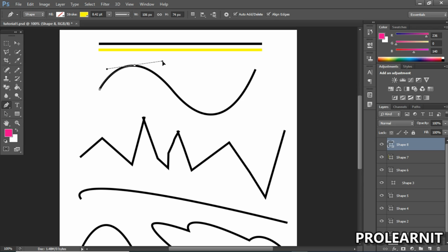I can just release my shift, and then I just click the left mouse button and draw this line. You can see over here, friends, when I'm satisfied with the point, I just release. Now I have that particular curve, and then I can come over to this section and click, and I don't release my left mouse button. I'm looking to see if I'm fitting my line with the line that already exists, and I just release. You can see over there, friends, I already have this shape.